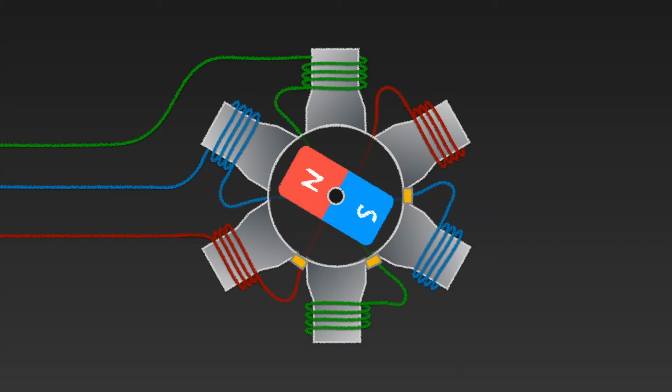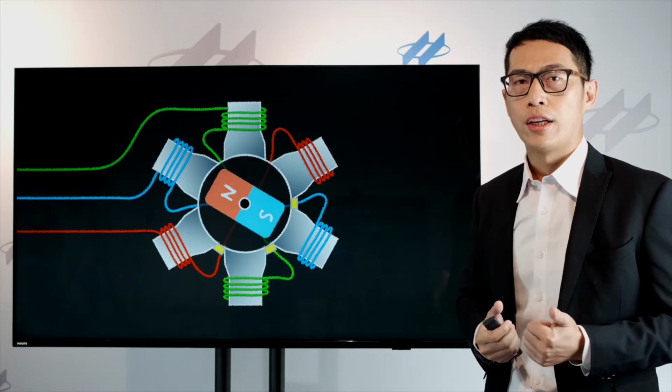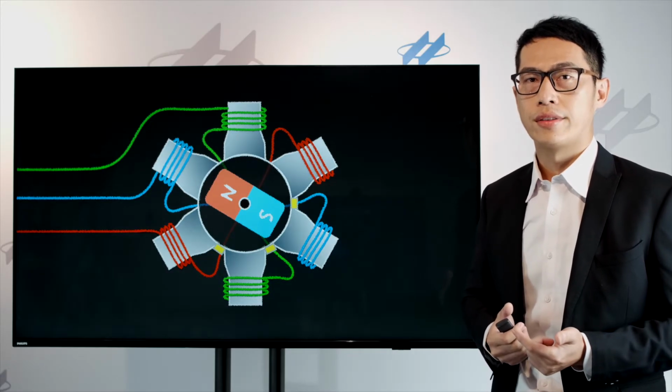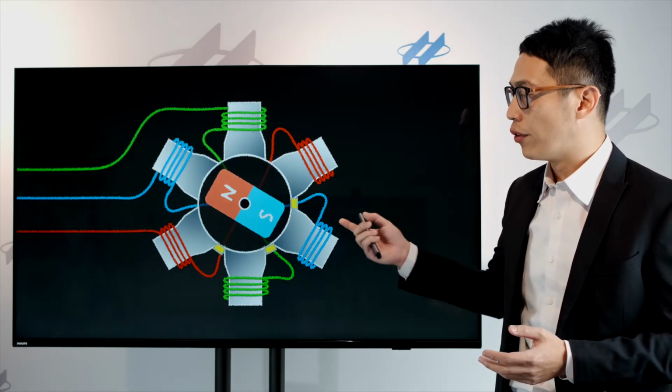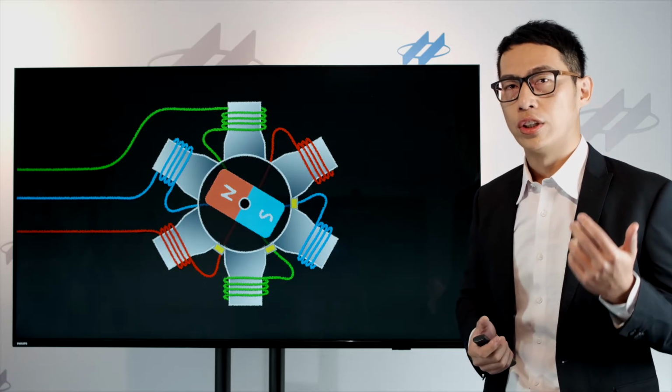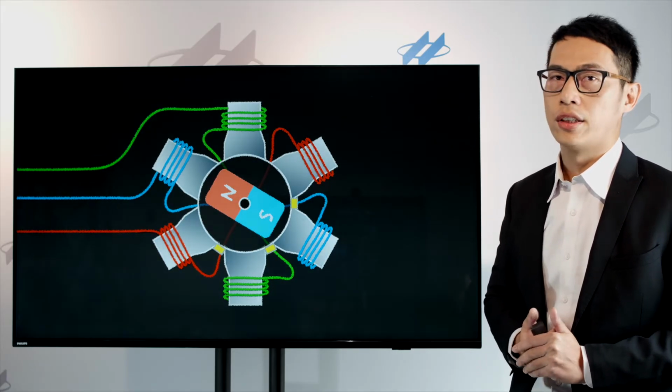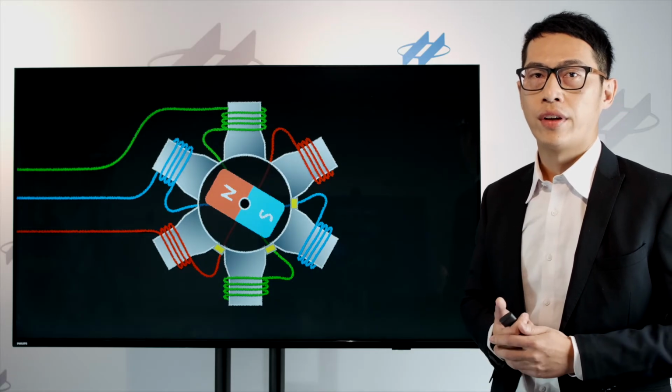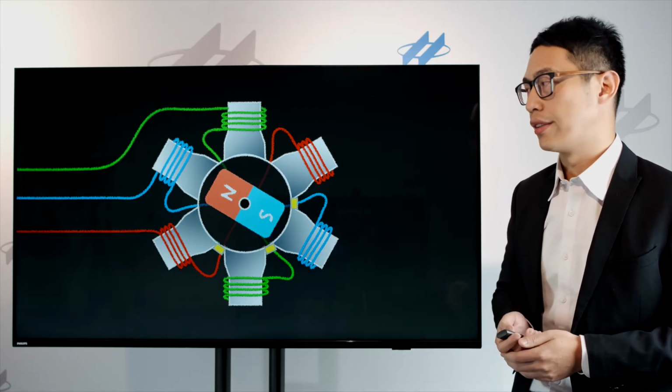And here is the BLDC motor. This is the BLDC motor, and the BLDC is very similar to brush DC motor, but one of the main differences is that it is without brush. The advantages of BLDC are higher performance, lower maintenance, and less noise due to the lack of brush. Also the longer lifespan, but of course it's expensive and the control is complex.